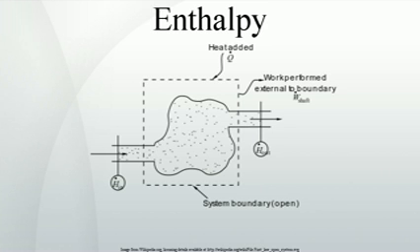There are then two types of work performed: flow work described above, which is performed on the fluid, this is also often called PV work, and shaft work, which may be performed on some mechanical device. These two types of work are expressed in the equation. Substitution into the equation above for the control volume CV yields the next expression. The definition of enthalpy permits us to use this thermodynamic potential to account for both internal energy and work in fluids for open systems.